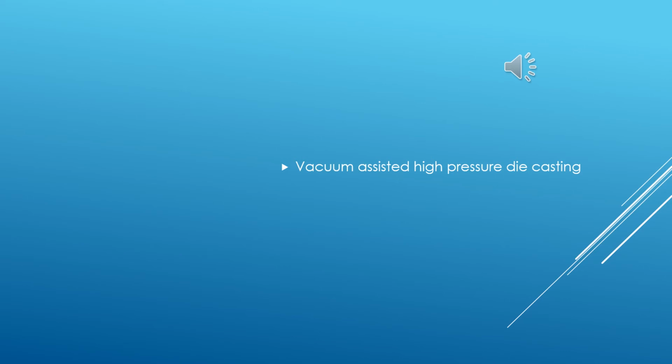As we know, one of the main causes of porosity in die casting parts is trapped air or gas that may occur due to the process principle during the conventional cold chamber die cast process and cannot be avoided even by good venting. In conventional die casting, the air and gases in the mold cavity are pressed into the overflow and the venting channels. However, there are still leftovers after this process, or the pressure in the mold may increase already in the first place by 1,500 to 3,000 bar depending on the venting application and plunger velocity. In the second phase, those volumes may be doubled or tripled.